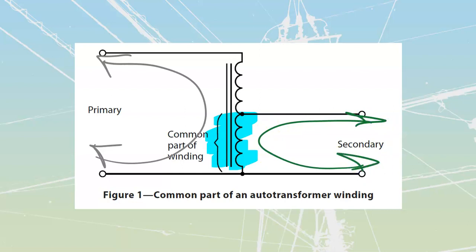There is going to be another part of the winding just up top over here. This is just going to be attached to the primary winding, always the longer one because there are more turns in the primary. There will always be a section that is only associated with the high voltage side. And in this case, they're showing us a high voltage going down to a low voltage. We can tell that just from the number of turns that are there.